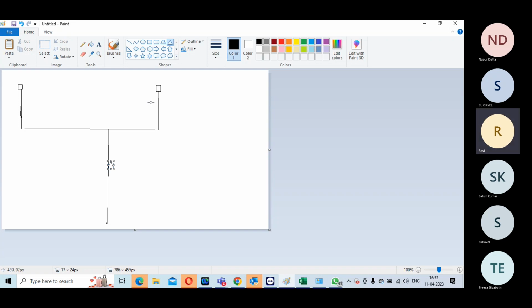Let's say you have a max fan out of 32 and 100K flops. So the equation is log base 32 of 100K. That's the number of clock buffers you are expecting, which means every clock buffer should drive 32 buffers. This is high fan out net synthesis. So it would be like some 3,000 buffers or so. That's all you should expect.